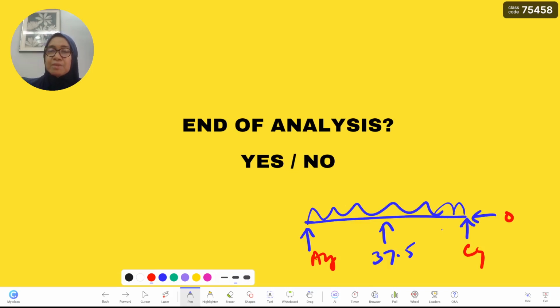In the flexibility method, we have to identify the redundant. Because the redundant is the problem, so we have to determine the redundant first. And the redundant we determine by solving the compatibility equation, which we actually derive from the principle of superposition. We name it as the compatibility equation.